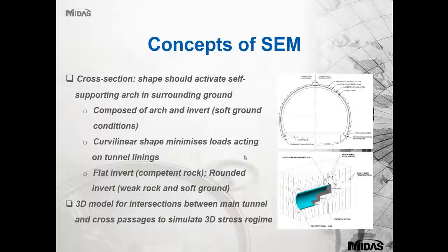So the advancing tunnel face causes changes in the initial vertical and horizontal stress conditions of the virgin ground. At the tunnel face, the stress flows in three ways: around the tunnel opening, arching ahead of the tunnel excavation, behind it into the newly constructed initial lining in the longitudinal direction, and to the sides of the opening in the perpendicular direction, which I've just highlighted with the mouse. So, such a three-dimensional state of stress can only be analysed through a three-dimensional finite element analysis.